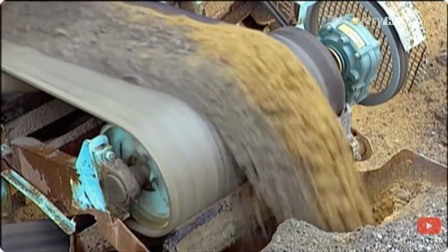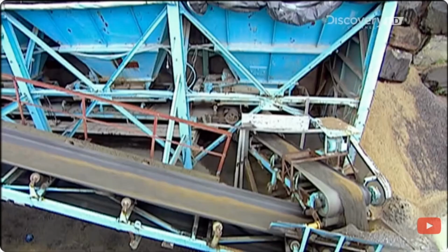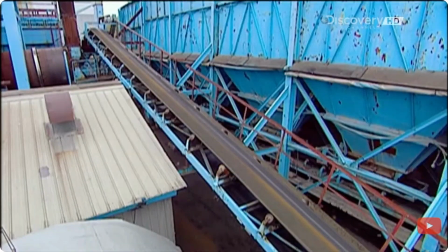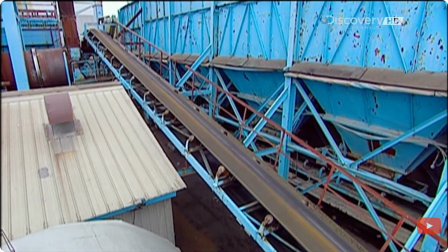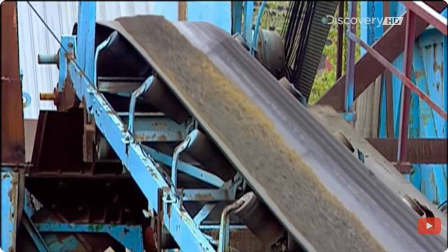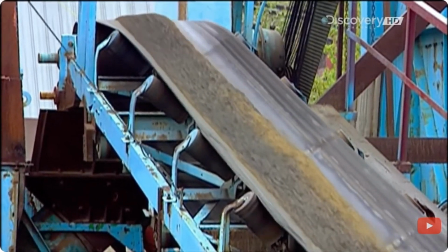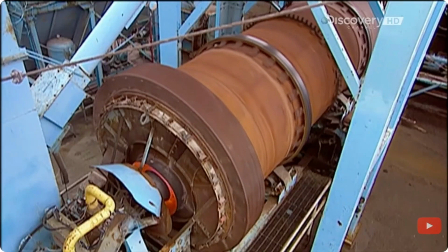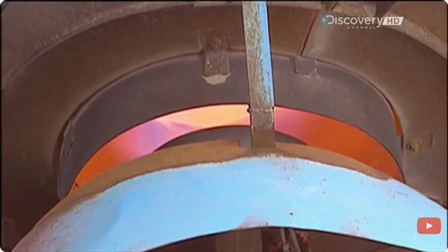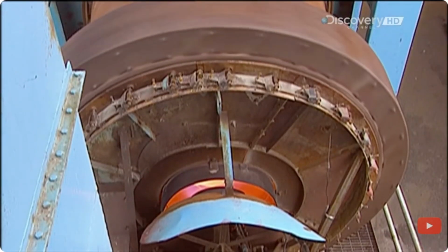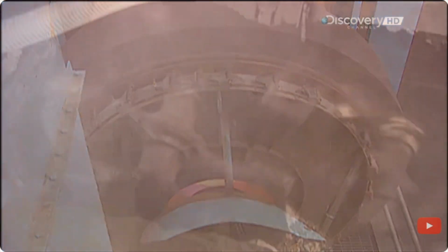The belts lead to a main collecting belt that dumps the combined ingredients onto yet another belt that leads to a dryer. The drying process, which takes about a minute, removes all traces of humidity. This will enable the materials to bond better with the asphalt cement. Screening equipment then re-separates the dried ingredients, making it possible to weigh out precisely the required amount of each one. Everything then goes into a mixer.